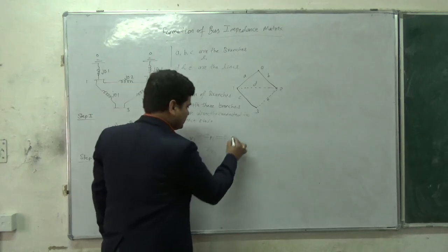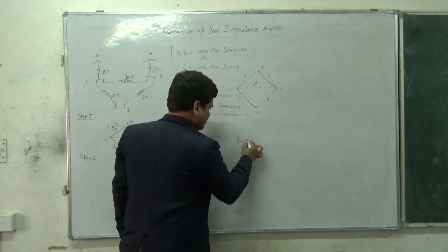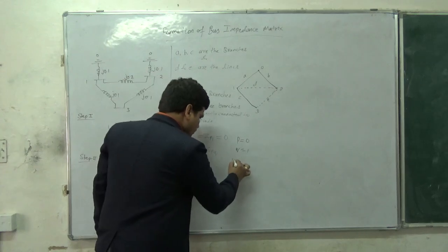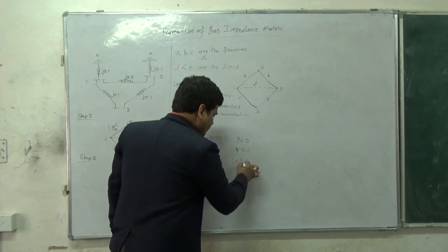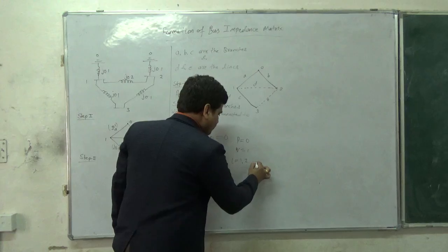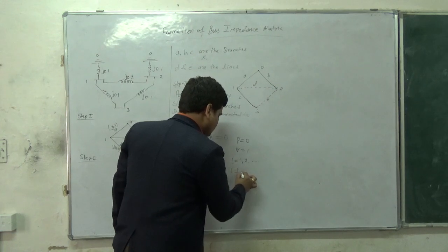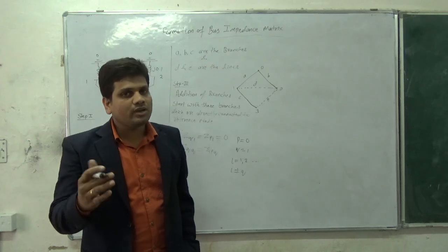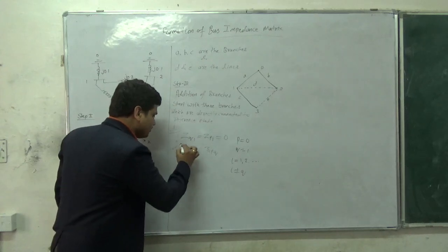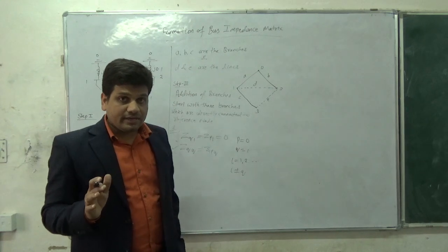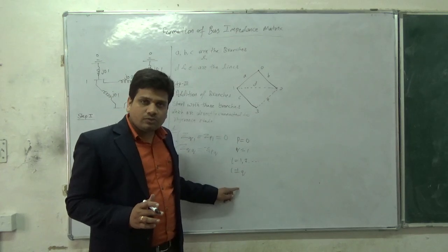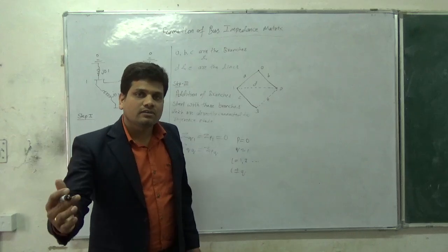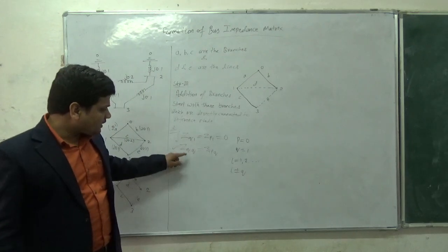I can go from 1 to the number of buses, with I not equal to Q. When I becomes Q, switch to formula number 2, that is for the diagonal element. I am repeating it again: when I becomes Q, don't go further, just switch to the second formula for the diagonal element.